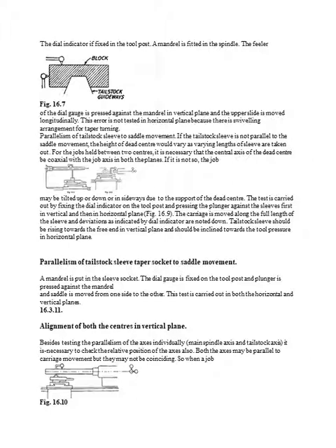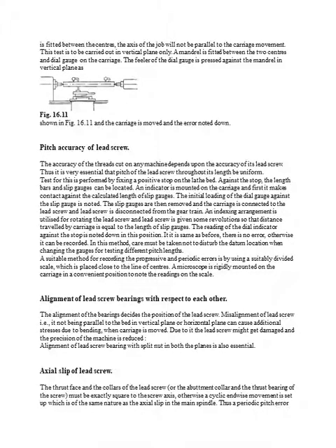Alignment of both the centers in the vertical plane. And the collars of the lead screw must be exactly square to the screw axis. Otherwise, cyclic endwise movement is set up, the same as the natural axial slip of the main spindle.